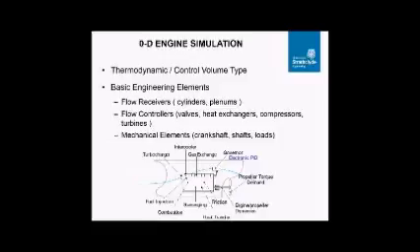So, in the zero-dimensional simulation, the engine model is a control volume type model that calculates the cylinder processes in a degree-by-degree crank angle resolution. The control volume models treat an engine as a series of thermodynamic control volumes interconnected through valves or ports.